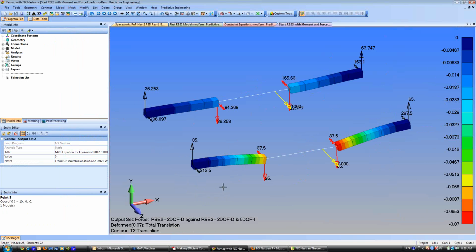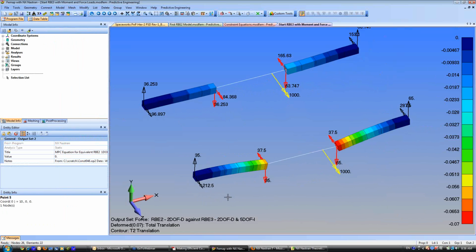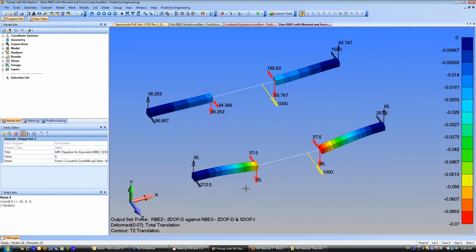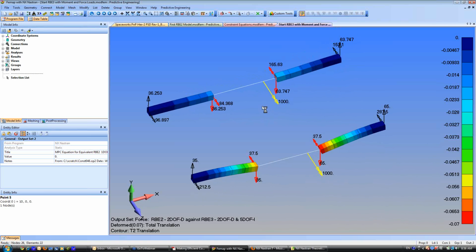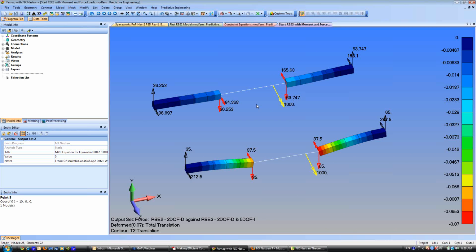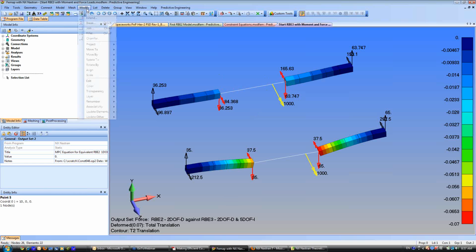Okay, close that out. Our simple beam model, all 6 degrees of freedom are fixed at the ends. The model's 15 units long in all. Each section is 5 units. Then I put a straight moment load onto it, 1,000. And in the RBE2, it's completely rigid. So what you're doing on a completely rigid element is defining the motions at these 2 points.